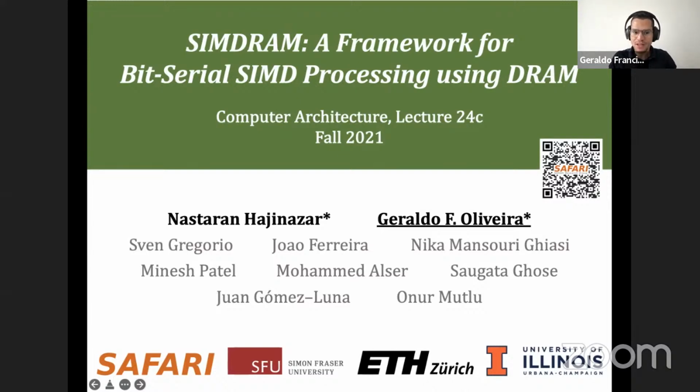That is enough to enable the coherence between the CPU and the SIMDRAM when you're doing the SIMDRAM computation. It's costly, yes, it's quite costly, because the flush operation is quite high latency, but we can overlap some of that latency with the SIMDRAM operations.